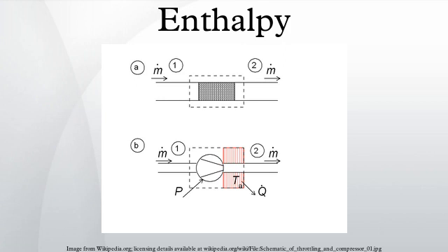If we choose the shape of the control volume such that all flow in or out occurs perpendicular to its surface, then the flow of matter into the system performs work as if it were a piston of fluid pushing mass into the system, and the system performs work on the flow of matter out as if it were driving a piston of fluid. There are then two types of work performed: flow work described above, which is performed on the fluid, and shaft work, which may be performed on some mechanical device.